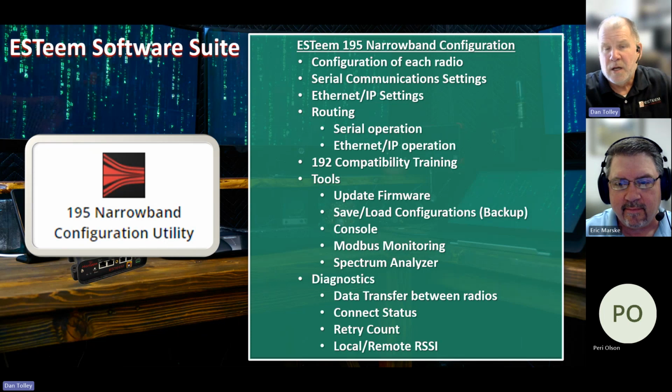set these things up. Also, we want to give you diagnostics. This is where we can actually transfer data between radios. We can verify the connection status. We can see how many retries there are, and what kind of RSSI or signal strength we're looking at, from both the local as well as what the remote is seeing. So this is the whole idea of this tool.